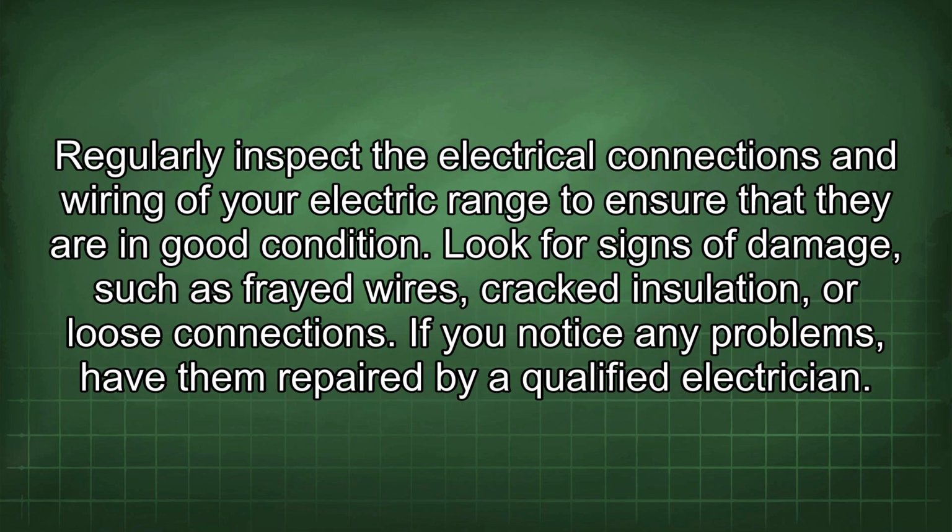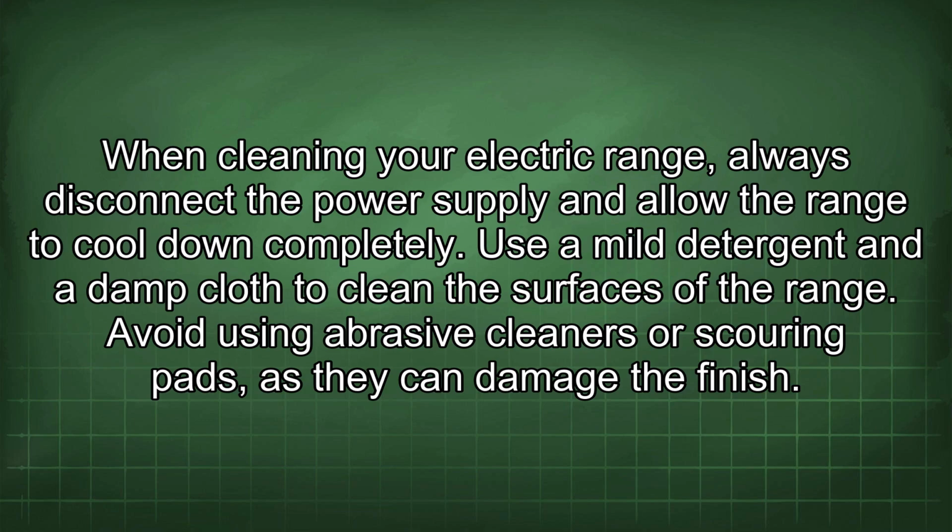Regularly inspect the electrical connections and wiring of your electric range to ensure that they are in good condition. Look for signs of damage, such as frayed wires, cracked insulation, or loose connections. If you notice any problems, have them repaired by a qualified electrician. When cleaning your electric range, always disconnect the power supply and allow the range to cool down completely. Use a mild detergent and a damp cloth to clean the surfaces of the range. Avoid using abrasive cleaners or scouring pads, as they can damage the finish.